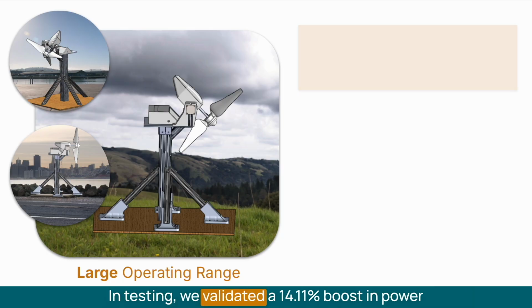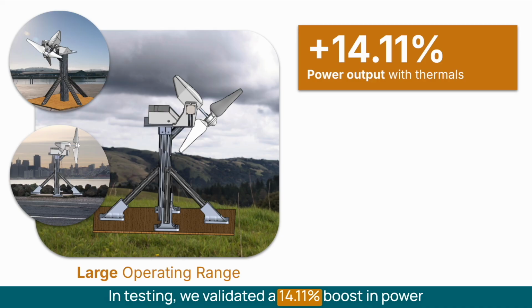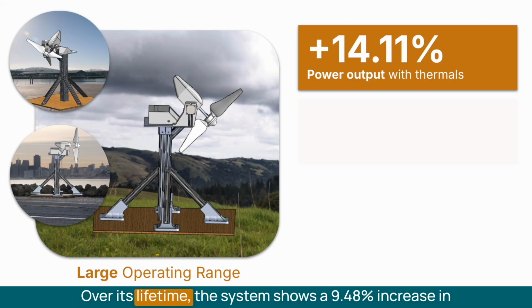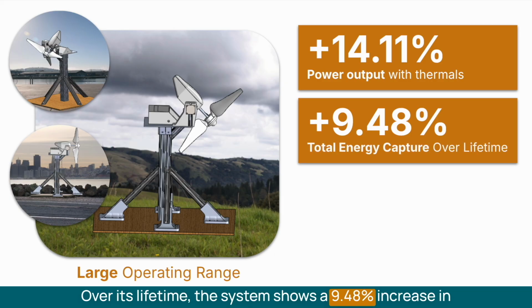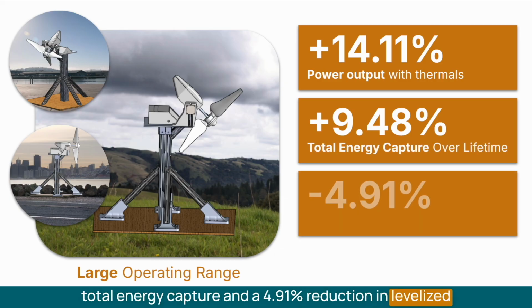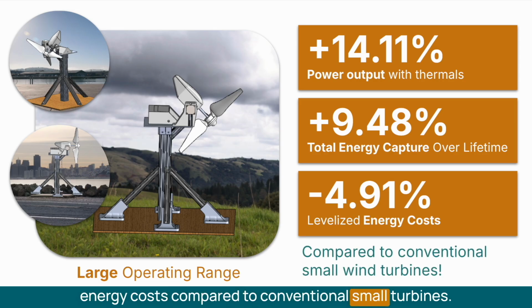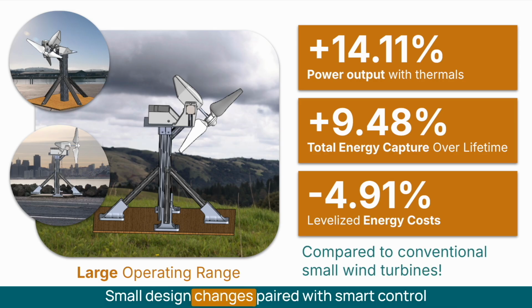In testing, we validated a 14.11% boost in power output from thermals, matching our simulations. Over its lifetime, the system shows a 9.48% increase in total energy capture and a 4.91% reduction in levelized energy cost compared to conventional small turbines. Small design changes paired with smart control can drive big gains in distributed wind generation.